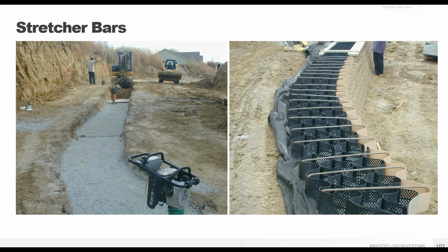When your wall has to curve beyond that gentle turn, stretcher bars are a best practice, as they'll hold the wall cells open to the optimal expansion while making that consistent curve radius needed. Note the portable compactors to compact the foundation layer.